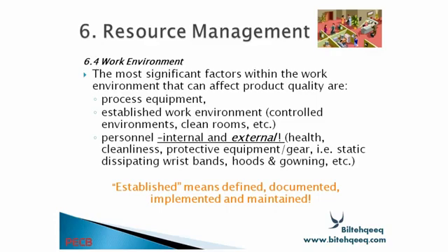Work environment. The most significant factor within the work environment that can affect product quality or process equipment. Establish work environment, controlled environment, clean room, personnel, internal and external, health, cleanliness, protective equipment, gear, static dissipative wrist straps, hoods, and gowning. Established means defined, documented, implemented, and maintained. And you have to establish this work environment. It means that it should be defined, documented, implemented and maintained.